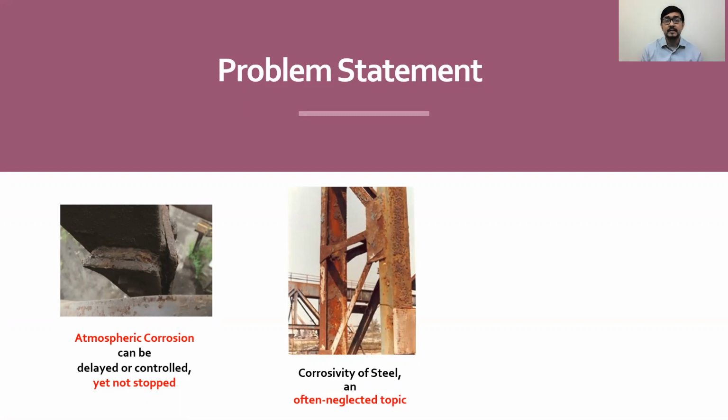Atmospheric corrosion, on the other hand, is an electrochemical process. It depends on the presence of electrolyte. The very usual electrolyte is water, which is also a universal solvent. Thin film electrolyte tends to form on metallic surfaces when a certain critical humidity level is reached, say approximately 60%.